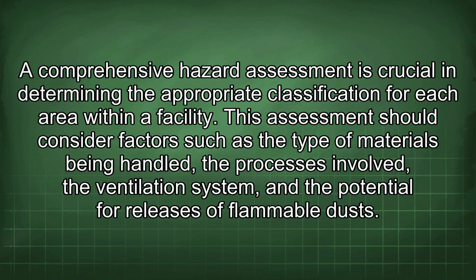A comprehensive hazard assessment is crucial in determining the appropriate classification for each area within a facility. This assessment should consider factors such as the type of materials being handled, the processes involved, the ventilation system, and the potential for releases of flammable dusts.